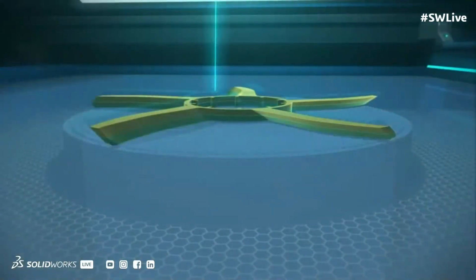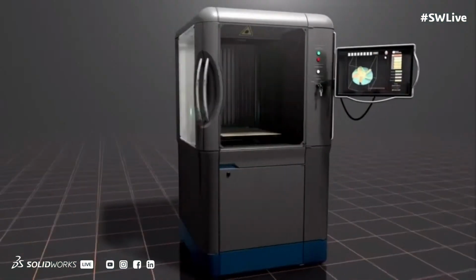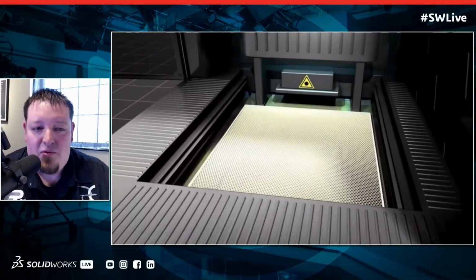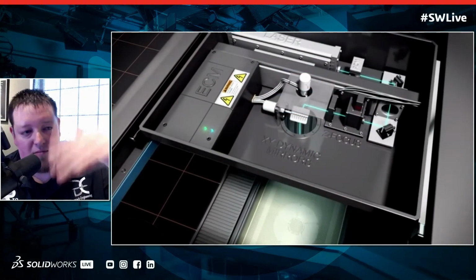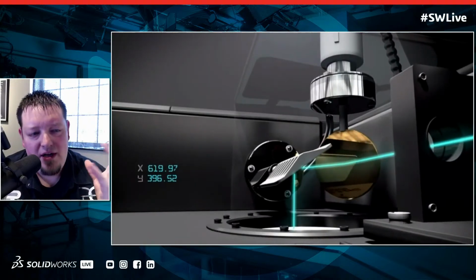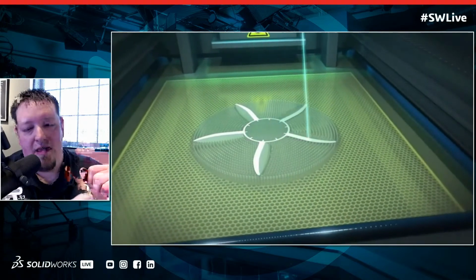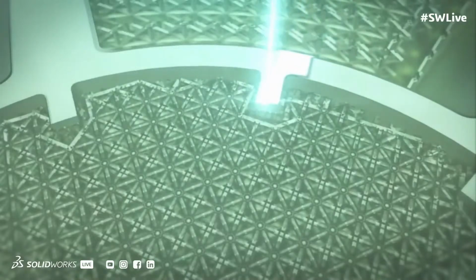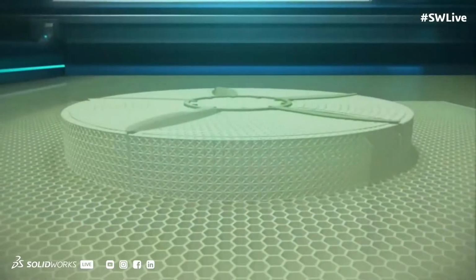So you can see here an example of that layer by layer construction, and you'll notice there's support underneath it. It looks like a kind of mesh underneath of it. That's support material. With SLA, you can't just have your part sitting in the vat. It would move all over the place and it wouldn't print. So that support material is there to anchor the part in position. And then when you're done, it's breakaway. So you just tear it away and you're left with your part and you throw your support away when you're done. And so, yeah, that is SLA or stereolithography in a nutshell.